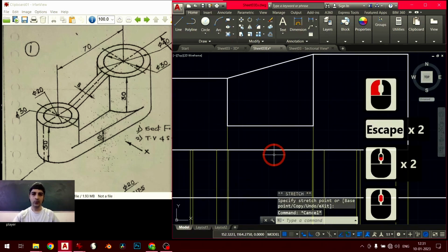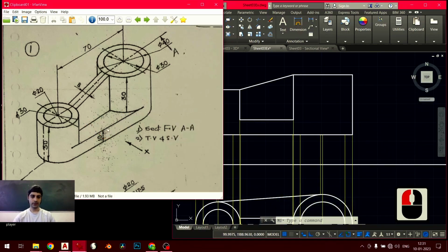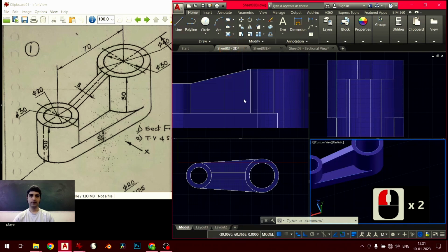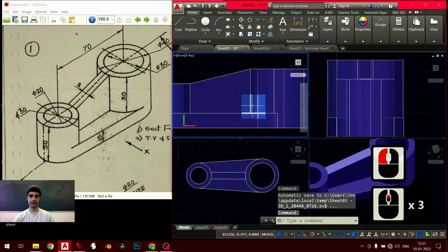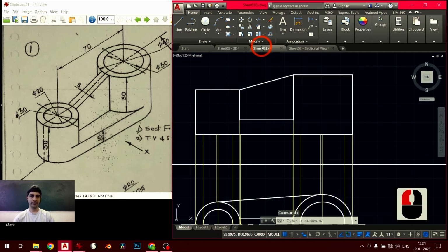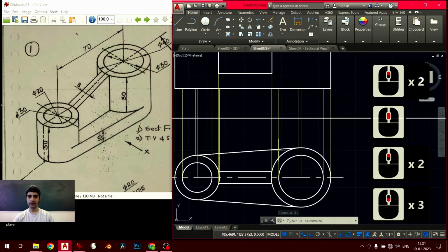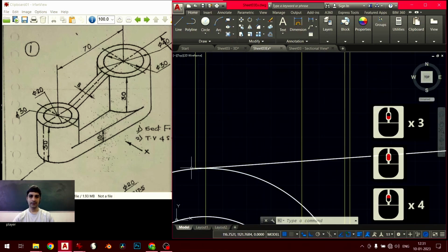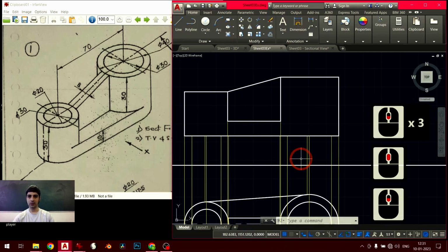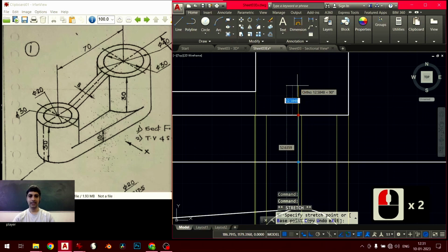All right. Now again, it looks like we are done, but we are not. So this base plate at the bottom, it stretches out into the curved surface until it becomes a part of it. Right? So if I look at what's happening here, this edge extends into the cylinder. So we'll have to do the same thing. And how far it extends depends on this projector here and this projector here. So let's stretch it out all the way to those ends, for which I'll just extend this out a little bit by, let's say, 10 units.